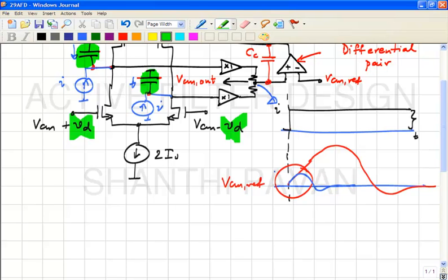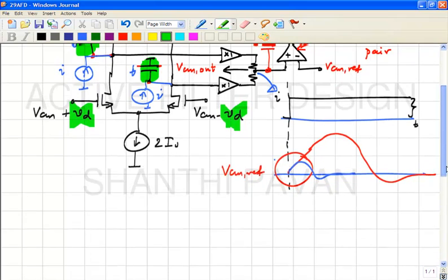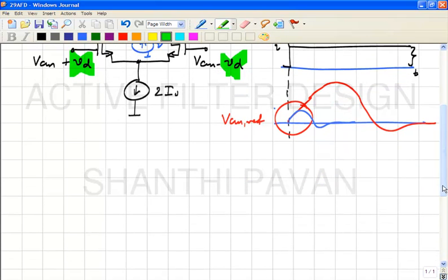Pushing a current into those two nodes means the voltage will attempt to jump up to infinity, and then the negative feedback loop wakes up, fixes the gate of the PMOS transistors and brings it all back to VREF, correct? So if you want to model the impedance as far as the common mode signal is concerned, what is a reasonable model given all these facts?